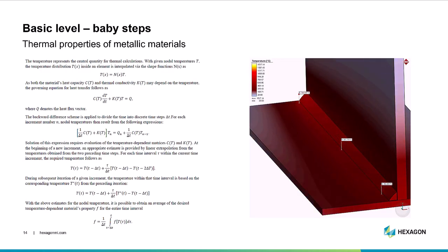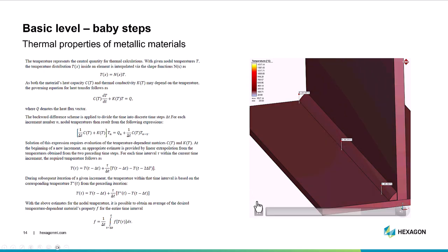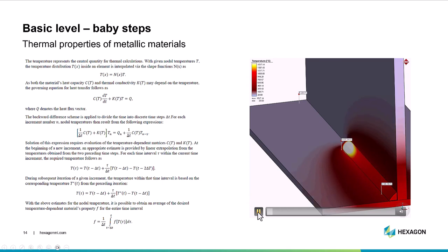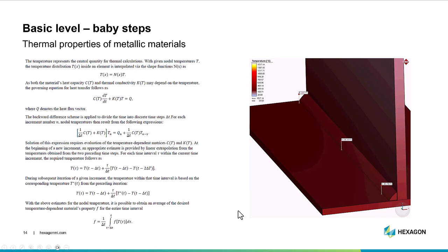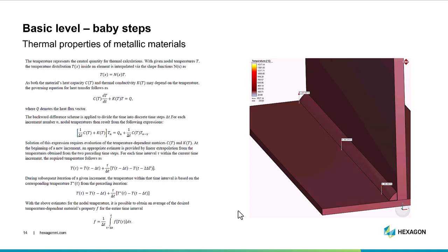This is a simple welding simulation. Again, the equations that you see on the left are just to illustrate where the data from experiments are going to be used in the numerical simulation of the process. Looking at the right, you see the animation of the welding process. It starts from room temperature, and then you add material, the filler material. It melts, and then it solidifies and causes some distortion and residual stresses in the structure. And this is going to lead to the behavior that you're expecting, for example, when looking at distortion of the part. You want to predict the distortion.